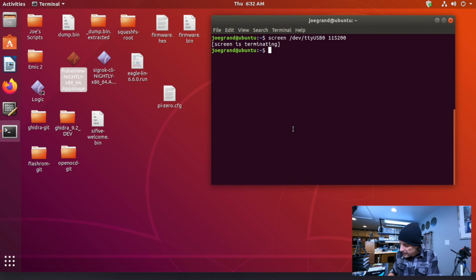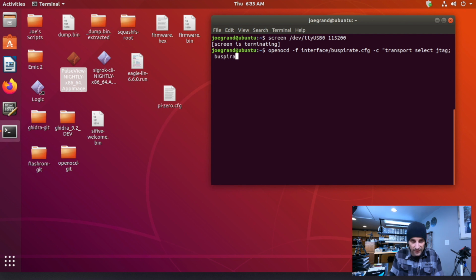We are going to type in that command. We'll launch OpenOCD with the interface of Bus Pirate. The way that the JTAGulator works for this mode is it emulates what's called the Bus Pirate binary protocol. And the Bus Pirate is an open source general purpose hardware hacking tool. They worked with OpenOCD to create this binary protocol to let the Bus Pirate, which is also a serial based interface like the JTAGulator, work with OpenOCD. So we're going to put in some additional command line settings, set our port, which is ttyUSB0.